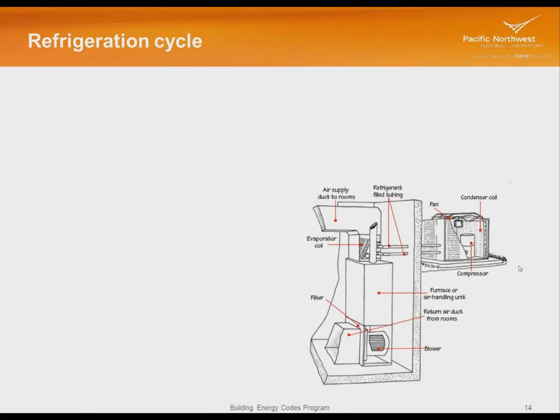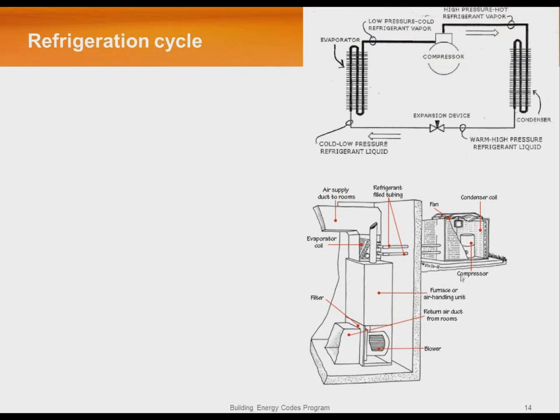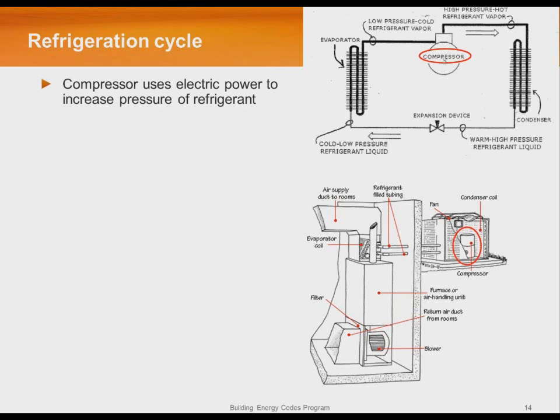So here's the same thing with the split system. This indoor unit is just like the diagram we walked through, and the outdoor unit is where the compressor magic is happening. Let's talk about refrigeration. If we look at a diagram of just the refrigeration circuit, we see we've got a compressor, a condenser, and an evaporator. Basically, what that compressor does is it takes cold refrigerant vapor, a gas, and compresses it, and when it changes the pressure of that refrigerant, it makes that gas hot.